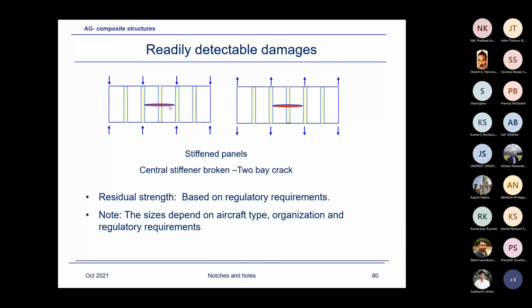The issue with these materials is, I think I might have talked about it during the certification talk, that with the improvement in the fibers and the matrix, the compression strength of a laminate is controlled by the shear modulus of the matrix, whereas the tension is controlled by the fiber strength. And there has been a lot of improvement in the fibers.